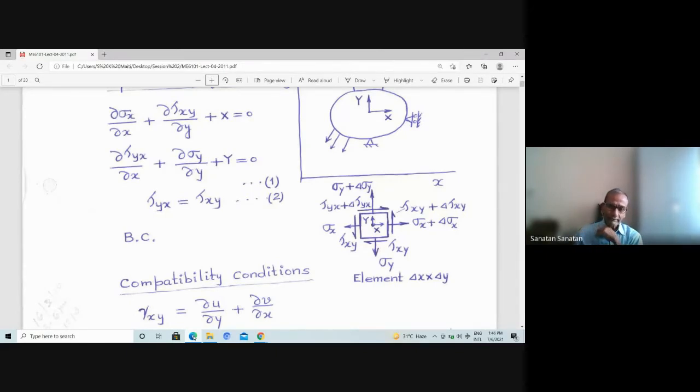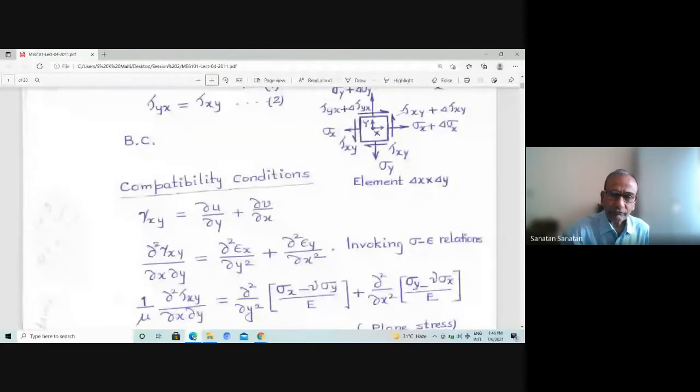So here also, we have two differential equations, but we have three unknowns. So therefore we have to find extra equations by considering the deformation. Let's see what that is. Sometimes this deformation condition is called the compatibility condition. In the case of that simply supported beam with fixed end, we consider that the beam does not rotate at one end, so its rotation is zero. That is a constraint on the deformation, and that's the way to find the extra equation. So we obtain the extra equations by considering the compatibility condition, what sort of deformation exists in the system. So how do we get the compatibility conditions?